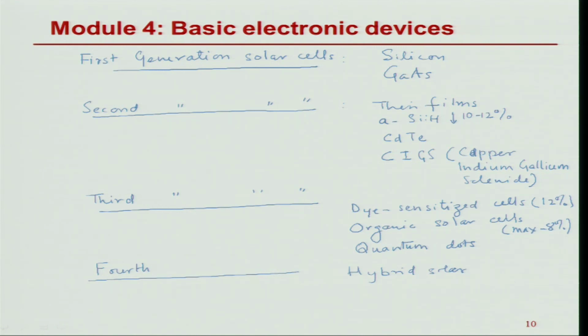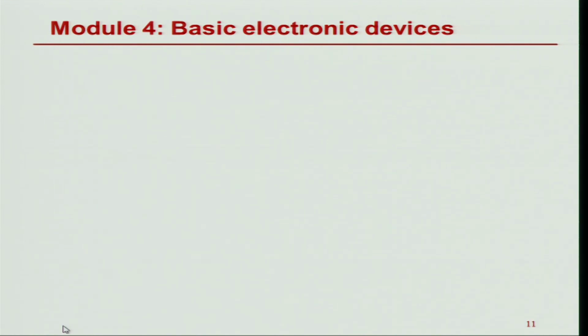So in summary, I have covered what a solar cell device is and how it works. We looked at a single junction p-n junction solar cell and looked at the loss processes if you have a very good p-n junction solar cell, and what the practical efficiency is that you can get. And as we saw, almost 50% is lost because we are not able to absorb it. It is lost in the absorption process itself, and hence a tandem cell or increasing that absorption enhancement is one of the ways of trying to get back some of that efficiency.